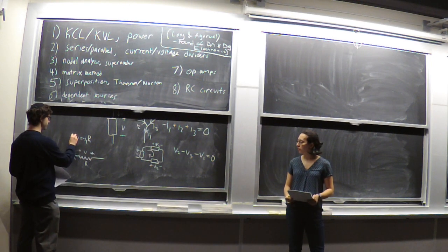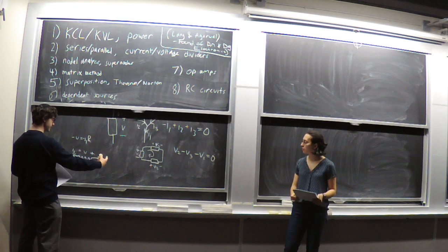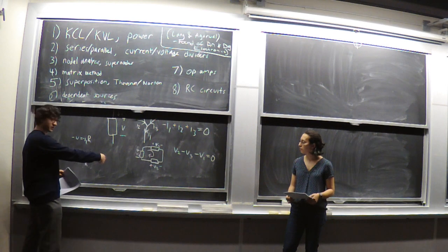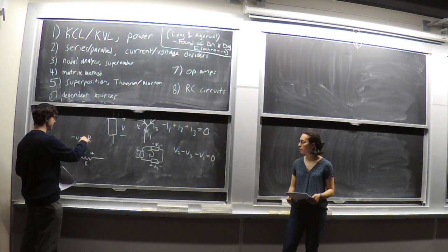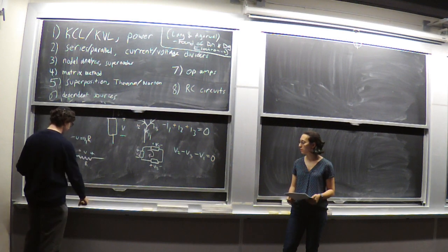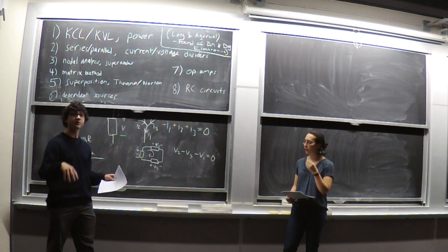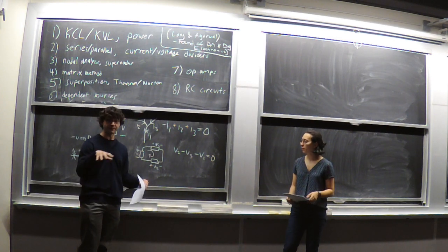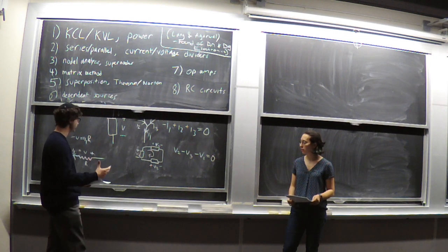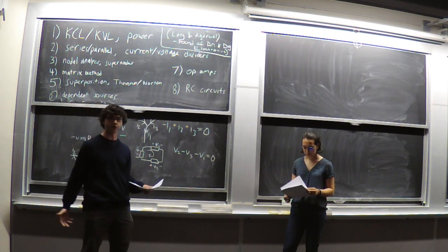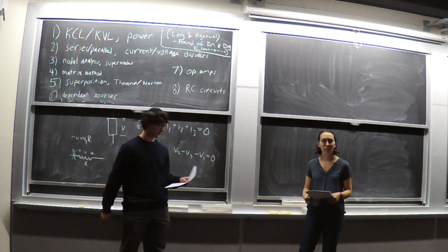Because we just flipped that, but if you notice, I could have just as easily drawn the I1 over here, and then we would have our normal situation where the current was going into the positive side, and we could drop both negatives. But the idea is that you can define these currents and voltages in your circuit whichever directions you want, but once you've defined them, you have to keep them however you've defined them, and then the positive and the negatives should follow from whether the current's going into the positive or negative terminal of your devices. We good? All right.